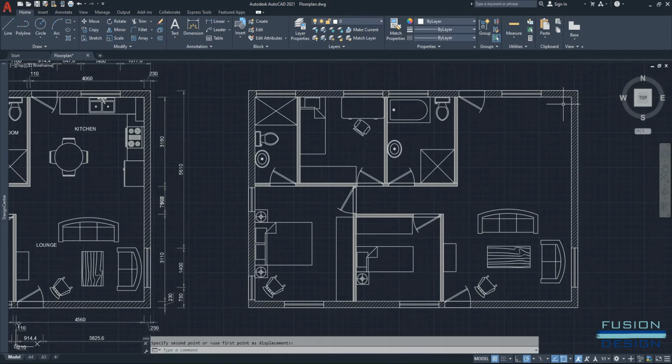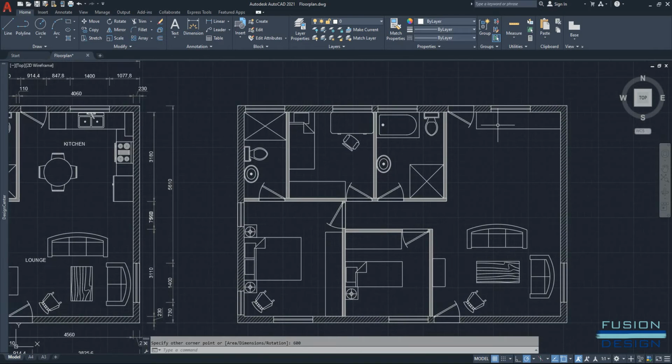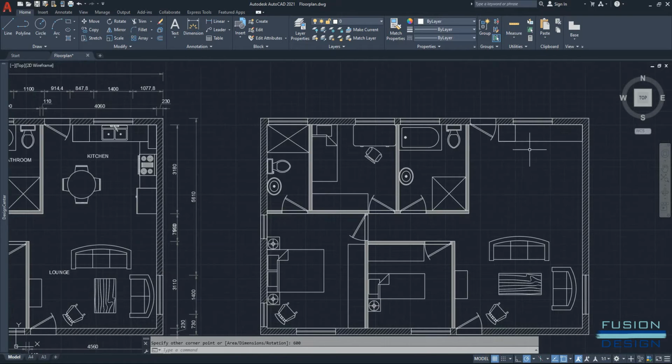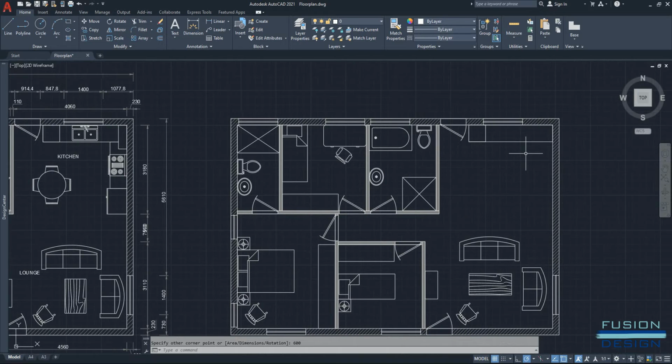I'll start in the top right hand corner and draw a rectangle. I'll make that 3000 millimeters, press tab and type in 600. Then I'll draw another rectangle and that'll be in fact a square, so I'll type in 600, press tab and 600 again. Press enter. Then I want to repeat the process of the rectangle on the other side, so I'll just press enter or spacebar.